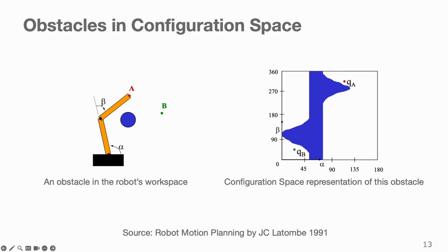And it's important to understand that this is how roboticists used to do motion planning in the 90s and in the 2000s. So the standard approach back then was to explicitly construct these configuration spaces and translate the obstacles into the configuration space, and then search for a path that stayed in the free space, as you can see in the next slide.